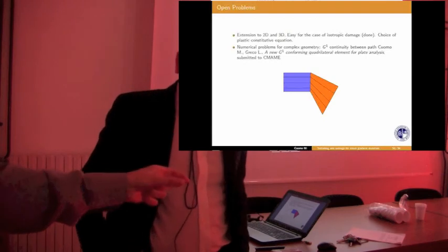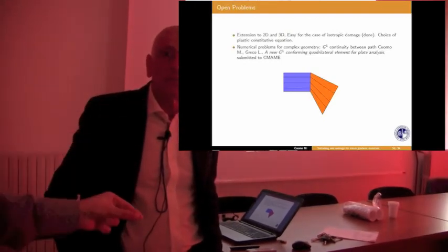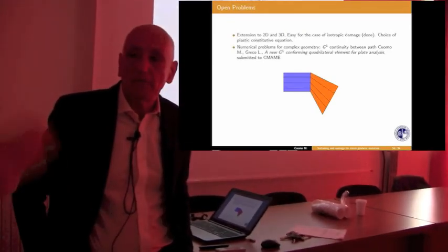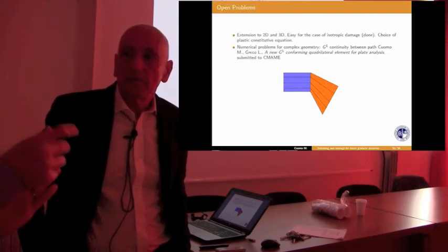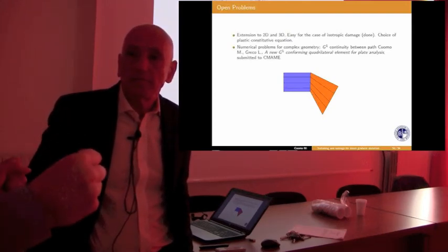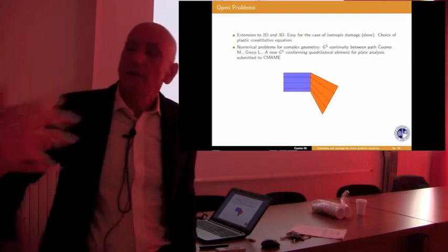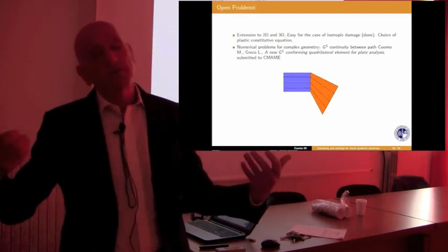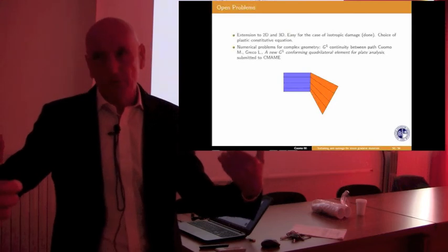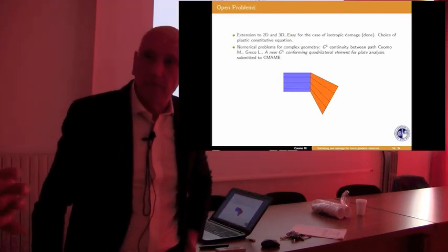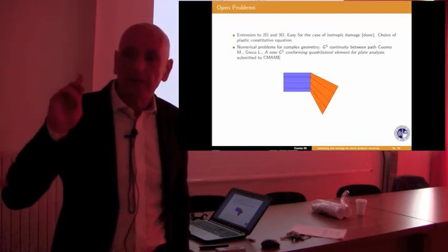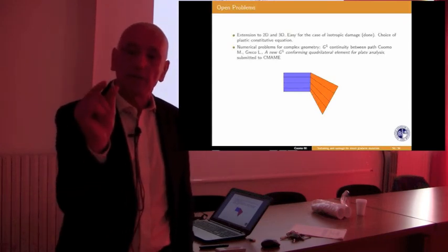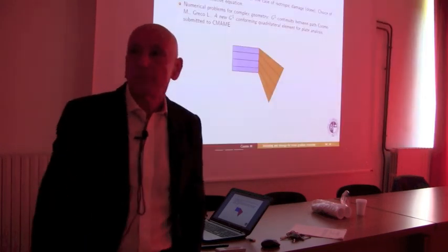And if you keep pulling on it, will the damage zone grow or will it remain concentrated? I mean, if you have localization in a damage zone with finite thickness due to the gradient model, and you continue loading. In this example, you cannot have finite thickness because it's homogeneous. The stress is not homogeneous, but the actual force is homogeneous. This is a combination of strain and gradient of strain. So in this case, you cannot get a limited band. It has to spread.